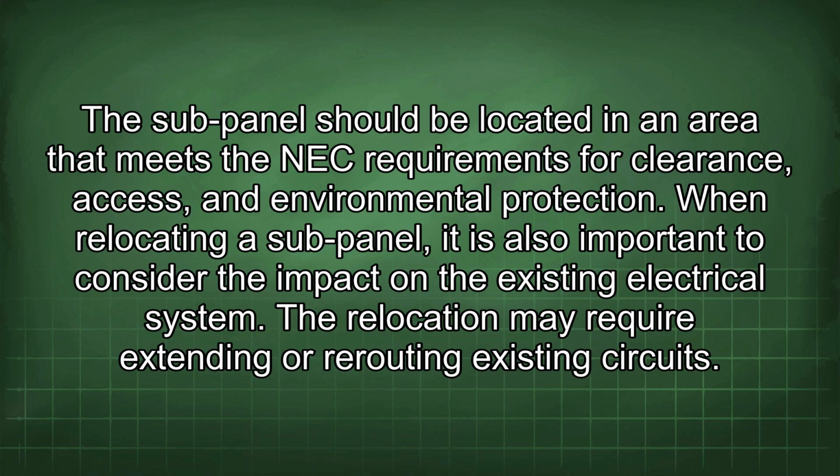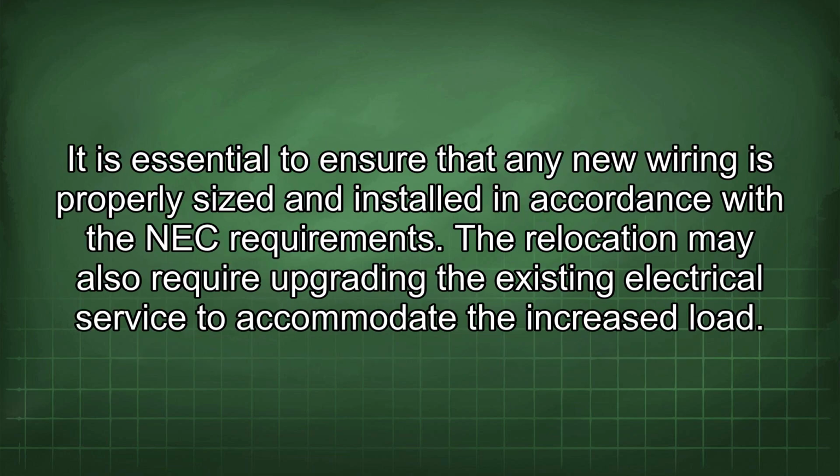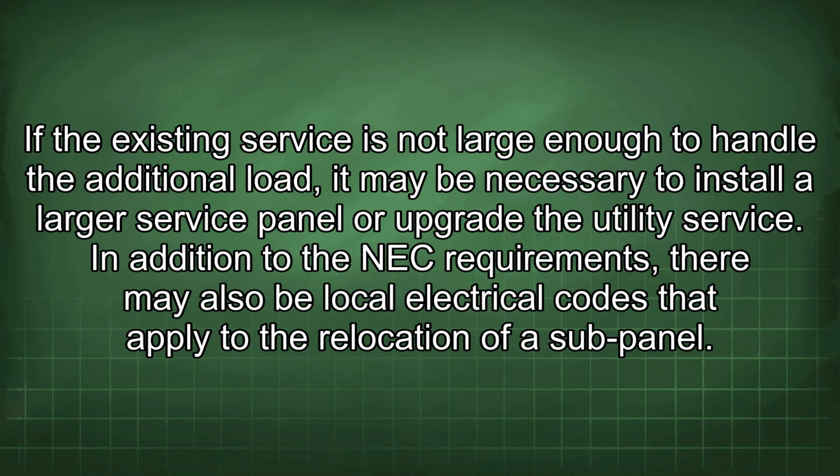When relocating a sub-panel, it is also important to consider the impact on the existing electrical system. The relocation may require extending or rerouting existing circuits. It is essential to ensure that any new wiring is properly sized and installed in accordance with the NEC requirements. The relocation may also require upgrading the existing electrical service to accommodate the increased load. If the existing service is not large enough to handle the additional load, it may be necessary to install a larger service panel or upgrade the utility service.